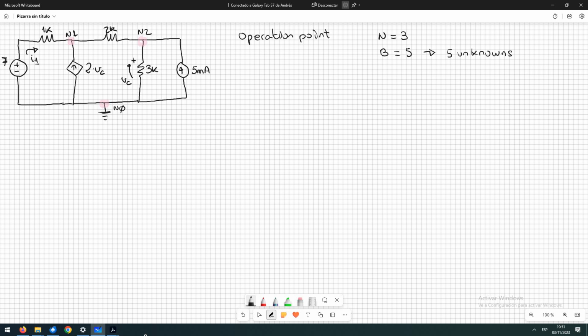In this second branch we have here a current source that is controlled. You know that there is a current source because we have an arrow inside, but it's controlled because the symbol is just a rhomboid, okay? It's a diamond, the symbol. So here the unknown is the voltage of this current source. I'm going to write it like this. That is the way we are used to.